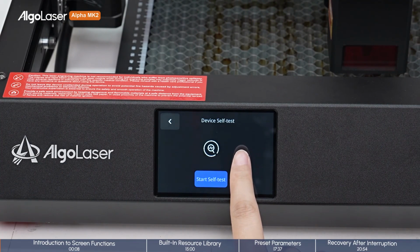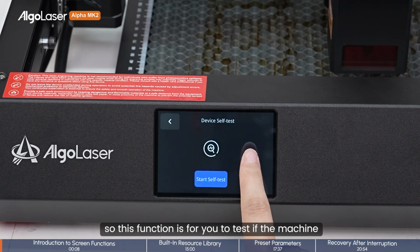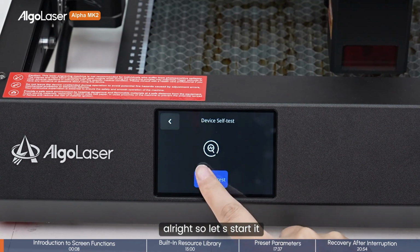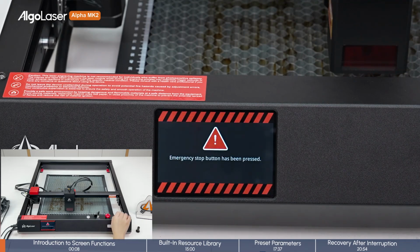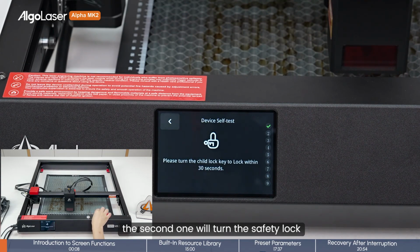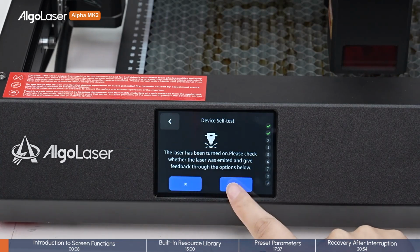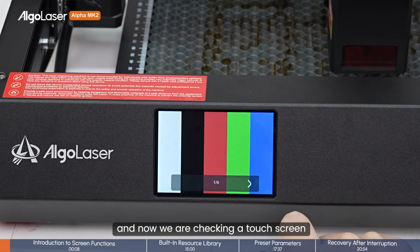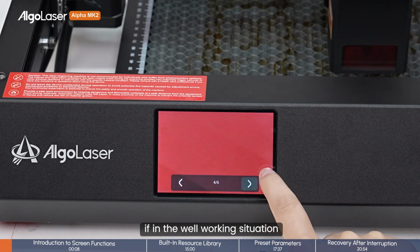Alright, now we need to do the device self-test. This function is for you to test if the machine is in a well-working condition. Alright, let's start it. First, we press the emergency button. Second, we turn the safety lock. Then we are checking the laser. We're checking the air pump. And now we are checking the touch screen. We need to check if it is working well.